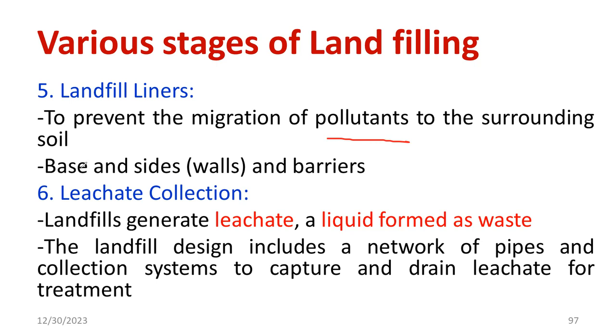That means we are creating some kind of border, a separate line or partition that we are supposed to maintain to prevent pollutants from reaching the surroundings. So we have to prepare the base, side walls or barriers that are required. That is the meaning of landfill liners. It has to be done by civil engineers.